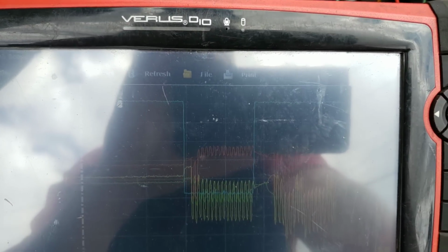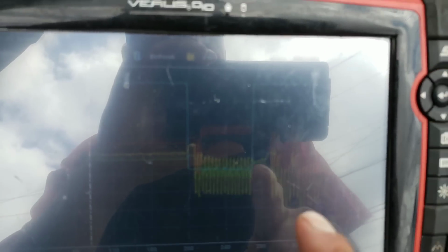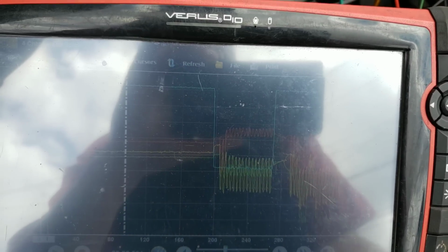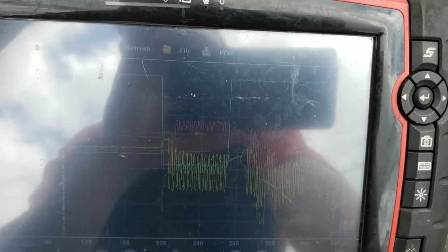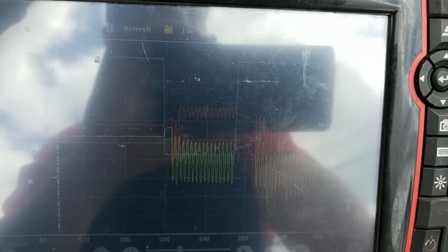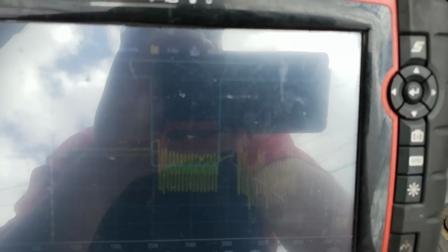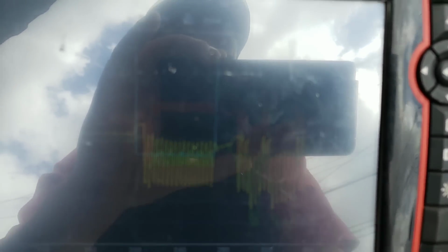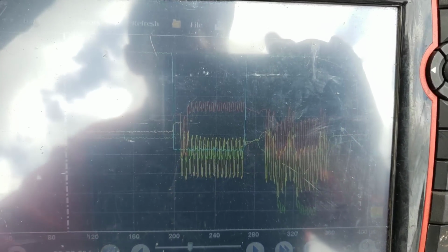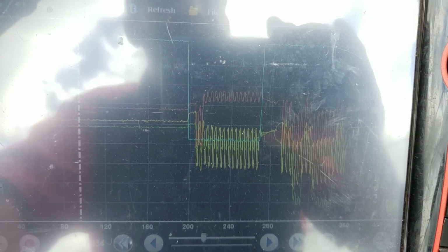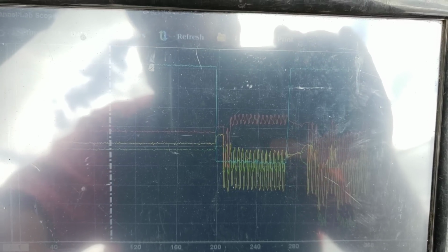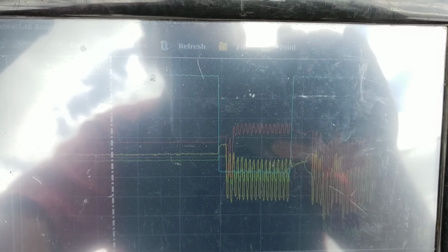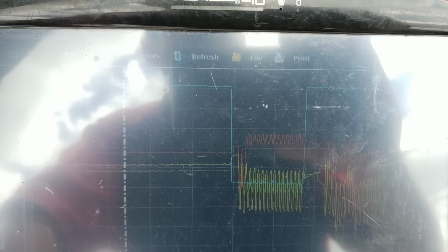If you have a ringing noise at the top of that signal, or even down here at the bottom where it comes down on the falling edge of the signal, then you're looking at something that's a higher resistance, or I should say, I'm sorry, if it's a ringing, it's low resistance on the clock line. So what you would get is something that looks a little bit more staticky, and I can't seem to keep the focus on. There we go. So you would start to see something that looks a little bit more staticky on the edges, and that's no good. We don't want that. That would be an indicator that there's a problem with the DME or the wiring going into the DME that's allowing it to build up more resistance.